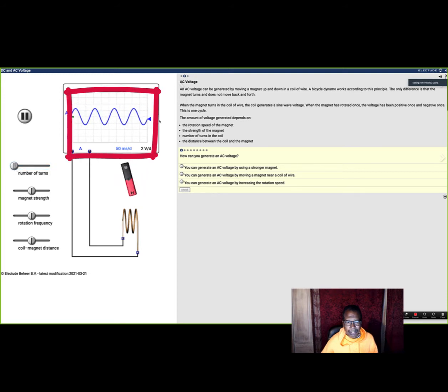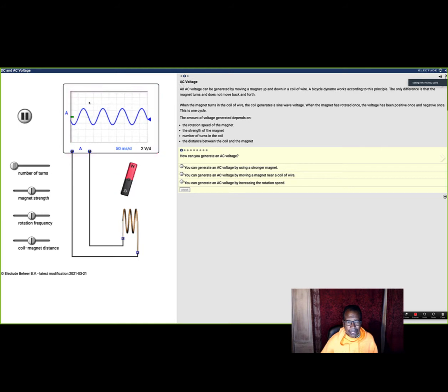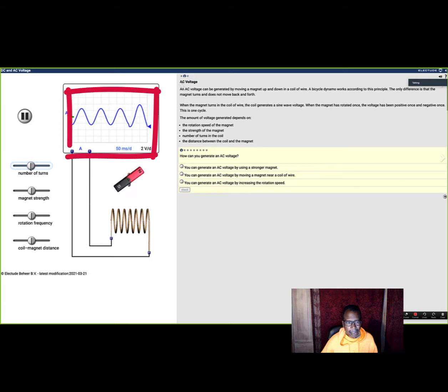A situation where I can recognize this is when a car will run off idle, because the magnetic field gets bigger, the permanent magnet signal or AC signal gets bigger, and I can trigger a module or the computer. But at lower speeds, because the coil winding is so weak, the amplitude, the height of it, is so small it cannot trigger the module. This is showing you that. Look at the magnetic strength. I'm going to increase it.